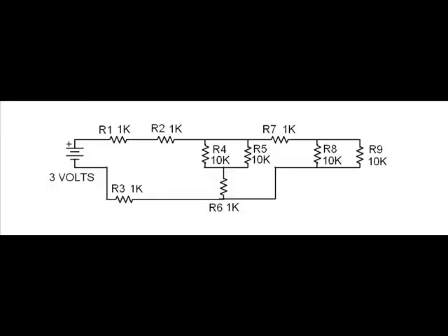This next section shows a more complicated series parallel circuit. All I'm trying to show you here is how to get that total resistance, and once you have that, we can calculate the current and resistance for everything else. I'll talk about that a little bit in a minute. So to solve the equivalent resistance for this circuit, we do it just like we did in the previous circuit. I find it easiest to start at the end furthest away from the source.